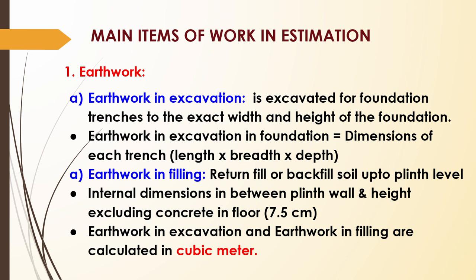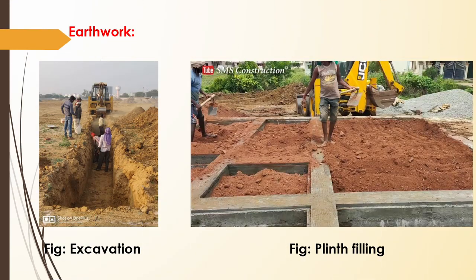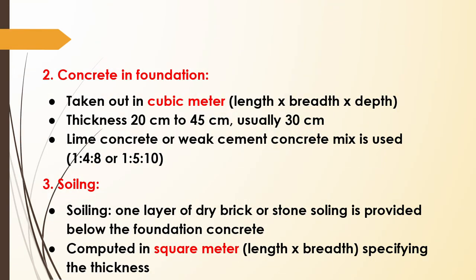So this earthwork in filling is also calculated by cubic meters, that is meter cube of soil, length, breadth into depth. So this is a figure showing earthwork in excavation as well as earthwork in filling or plinth filling. Now the second work is concrete in foundation. So before concrete in foundation, soiling.